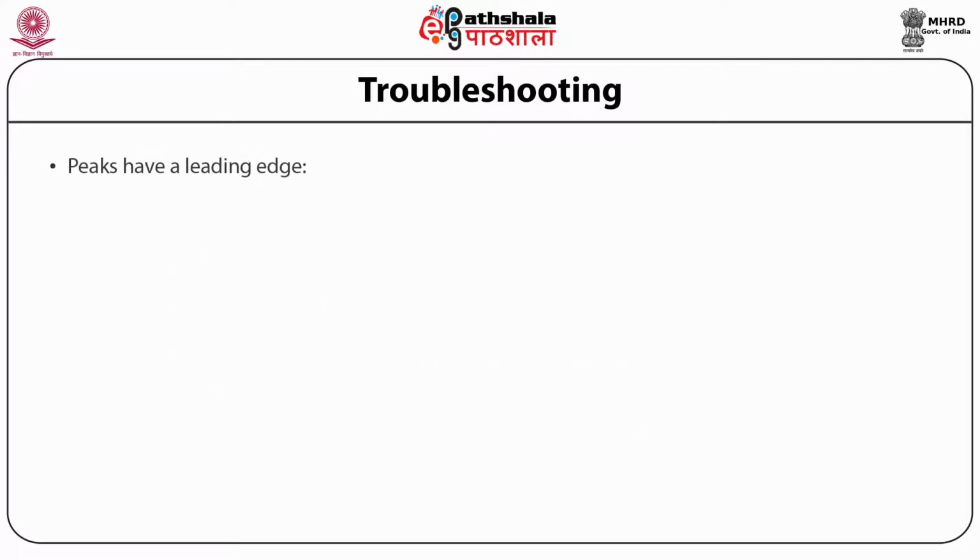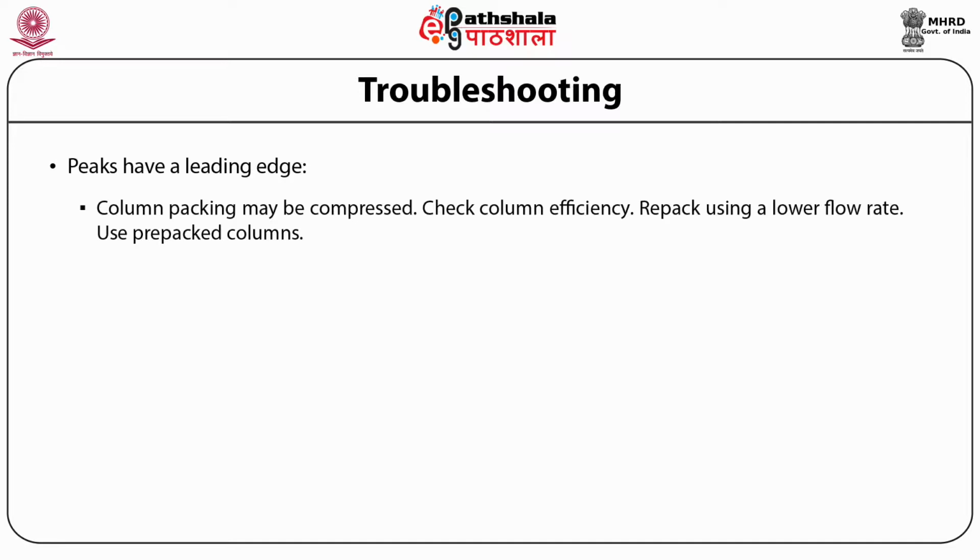What if the peaks have a leading edge? Now, in this case, the probable reason could be that the column packing may be compressed.